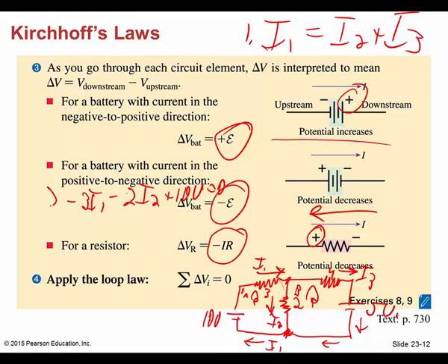So here's one equation, here's 2 equations. And then our third equation, I'm going to start right here, moving with current flow. So my third equation would be negative 4 I3. And you say, why is it negative? Because I'm going with the current flow, I'm dropping voltage. Then I hit the positive side of my battery, but I land on the negative, so that would be minus 5 volts. Then I come on around and back up this loop, going the opposite direction, so that would be plus 2 I2, equal to 0.